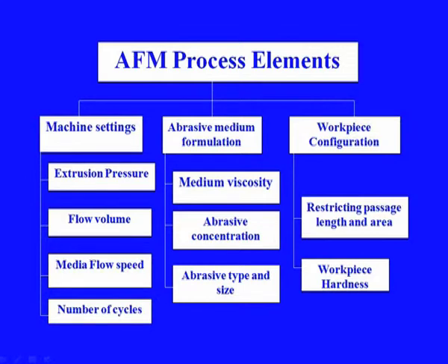On the other hand, abrasive media based parameters include media viscosity, then abrasive concentration in that carrier, and then abrasive type and size in that media. The workpiece based parameters include the passage length and area, and then workpiece hardness, etc.